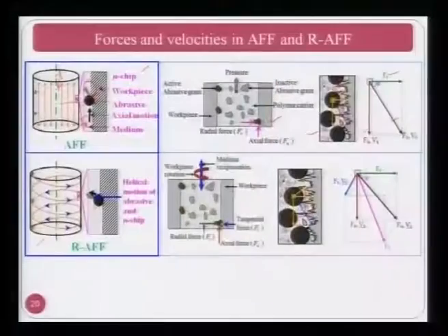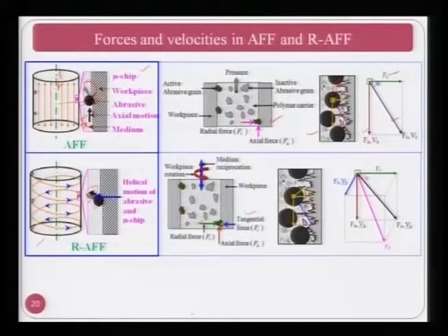In the same way, you can see here the abrasive particle, and material is removed in the form of a microchip. Now, in this particular case, the radial force is acting due to the elastic behavior of the medium. Then there is a tangential component Ft, which is due to the rotary motion of the workpiece with respect to the abrasive particle or vice versa. The axial force I have already explained. So, if you see the last figure, there is the radial force acting over there, there is a tangential force acting over the workpiece surface, and here is the axial force.